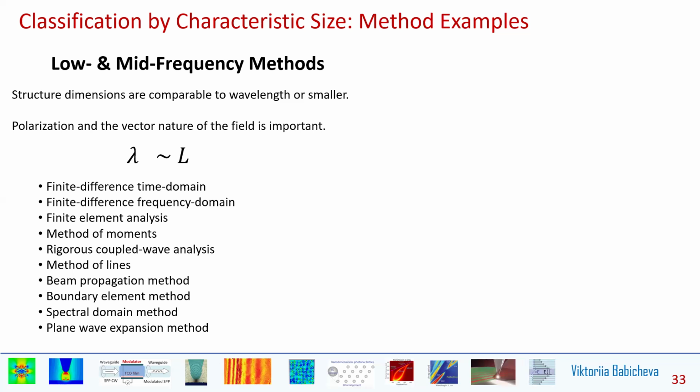Now I would like to sum up the preceding discussion, and one way to categorize a numerical method is to determine whether a specific numerical method targets the low, mid-wave, or high-frequency regime. Both integral and differential equation methods are plagued with instabilities, and when the frequency is extremely low or the wavelength is very long compared to the structure being probed, then this property becomes more pronounced. This is because we switch from the regime of wave physics to the regime of circuit physics. This transition indicates a change in the solution method when one goes into the low frequency regime.